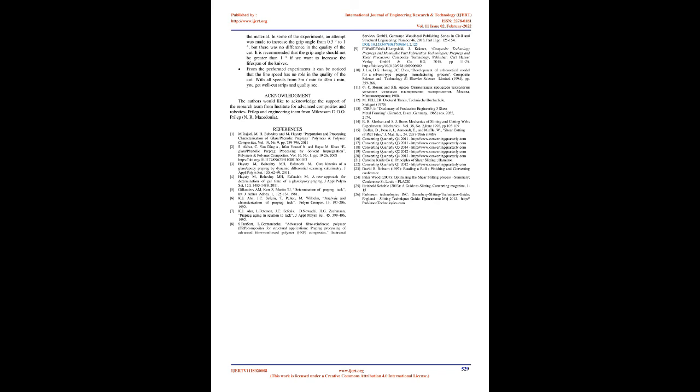V. Conclusion. From the performed experiments for different types of materials with different parameters during cutting, the following conclusions were made. The most important factor in determining the parameters for cutting UD prepreg is the type of material to be cut. The overlap of the blades should not change much for different thickness of the material.